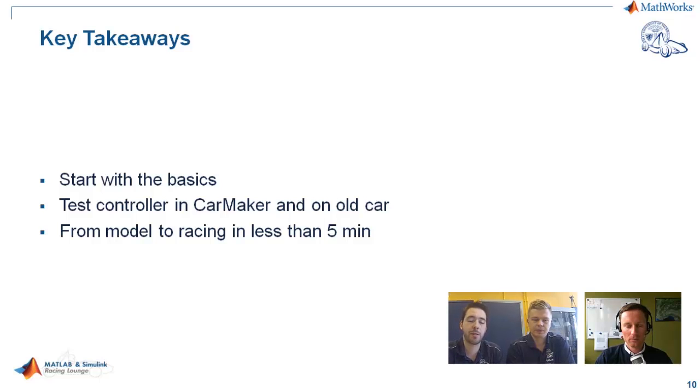Yeah, then we would also suggest that you start testing really early if you are building a controller. You can test your controller in CarMaker. What we also did is that we tested it on the old car. And it really allowed us to start testing around January or February, so some basic functions even earlier. There's really no reason to wait until the car is finished to start testing your control system.